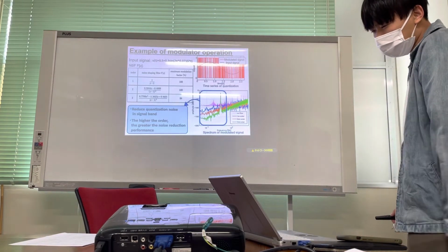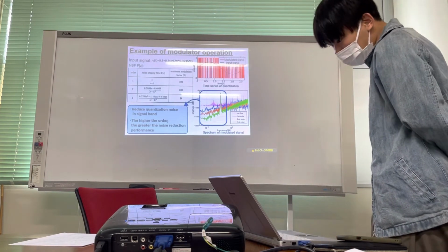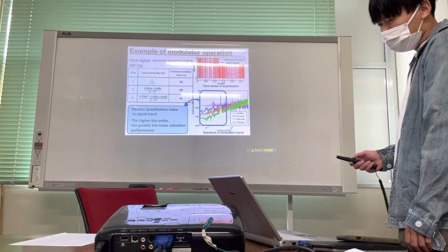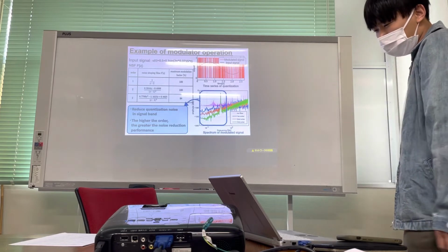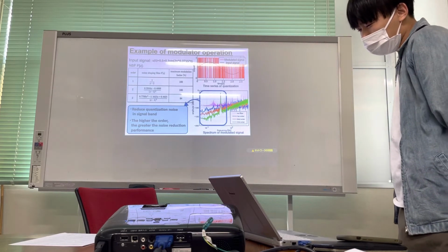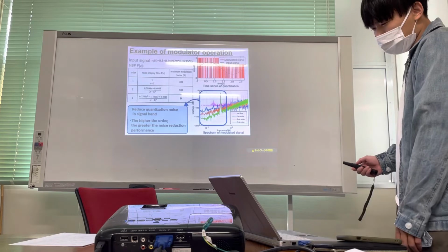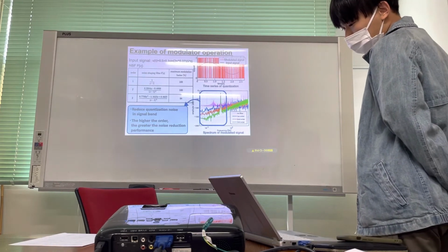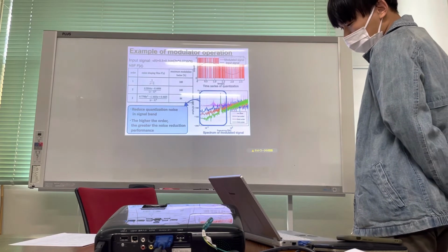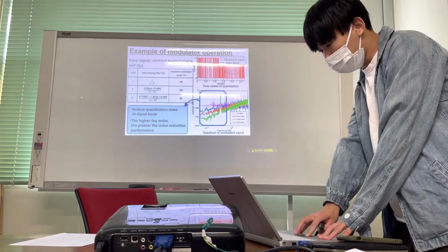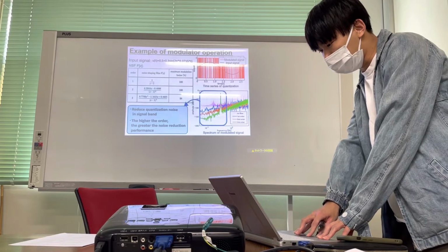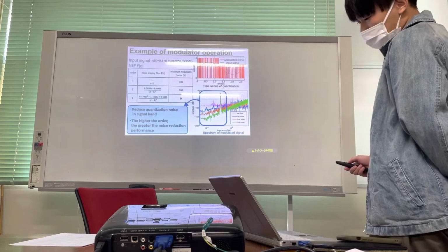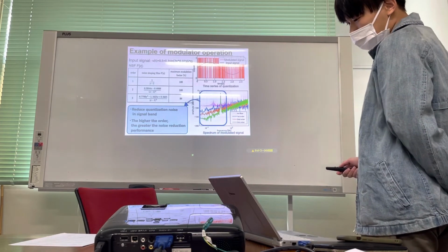Here is an example of the operation of the delta sigma modulator. We use this noise shaping filter and input a sine wave as the analog input. This figure is a comparison of the spectrum when only zero-cross control is performed and when delta sigma modulation is combined with zero-cross control. The horizontal axis represents frequency, and the vertical axis represents spectrum.